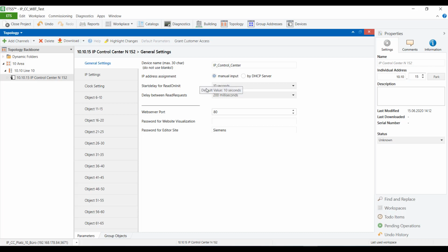The next two parameters control the behavior when a device restarts. Start of the query after bus reset means that after the configured time, the device starts with query telegrams, for example, status queries of lighting states. In order to avoid high telegram rates after a restart, the start time for the query interval can be adjusted.